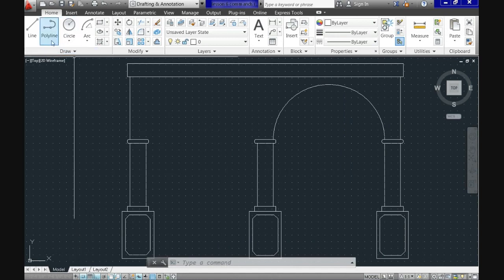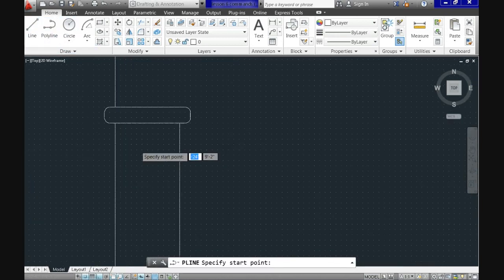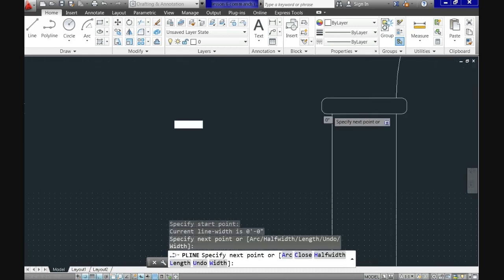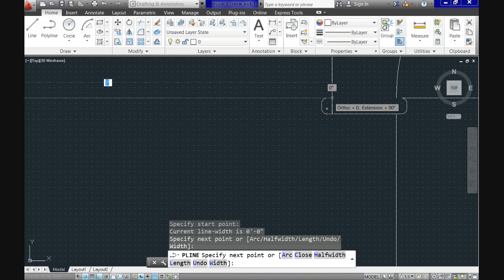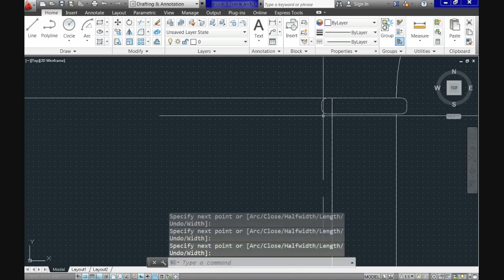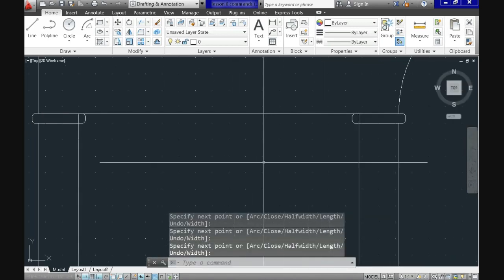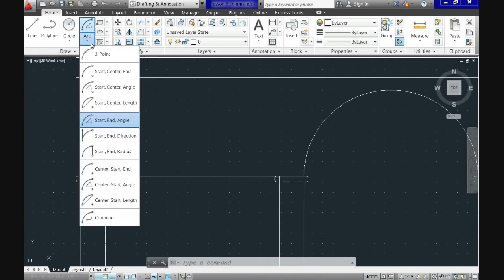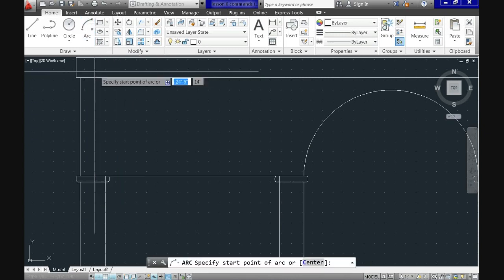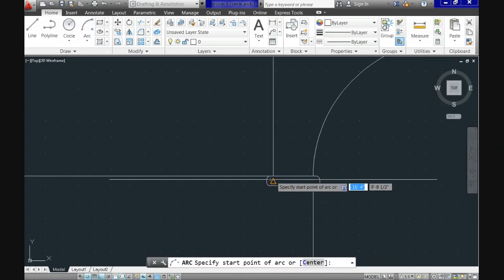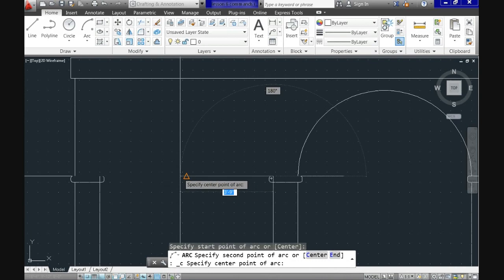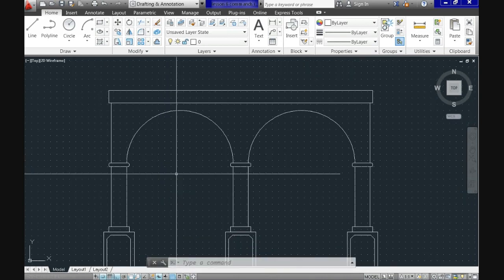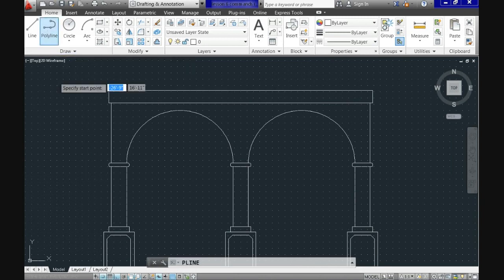Let's try now a different option. You can see how your selection is dependent on the information you have. I'll draw a reference P-line, so here I determine the center of this line, and because now I have a different option, I'll use the start, center, and end option, the second one from top to bottom. And CAD prompts you first point, center point, and end point. You select them in that order, and we just did the same without using the angle but a midpoint.